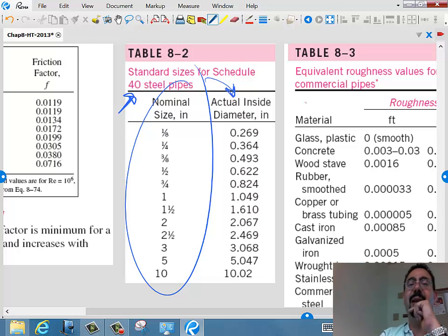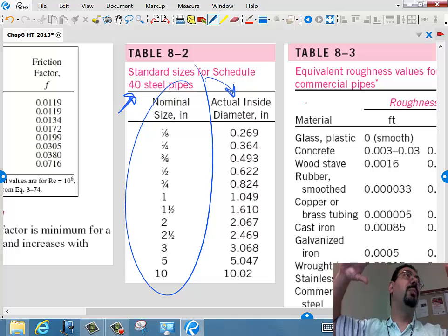So I also remember in that senior design project, we were trying to figure out what is the right diameter for the pipe. Of course you realize that if the pipe is really big, it would be very expensive. The bigger the pipe, especially since that pipeline was really, really long, the more expensive it is, right? Not just the pipe, but the valves connecting it and the fittings and all the protection, because you're supposed to protect it against water hammer. That's when suddenly a valve could close, the pressure would rise, and the pipe would rupture, right? And so you had to put in a lot of relief valves and stuff, especially because it was crossing a river.